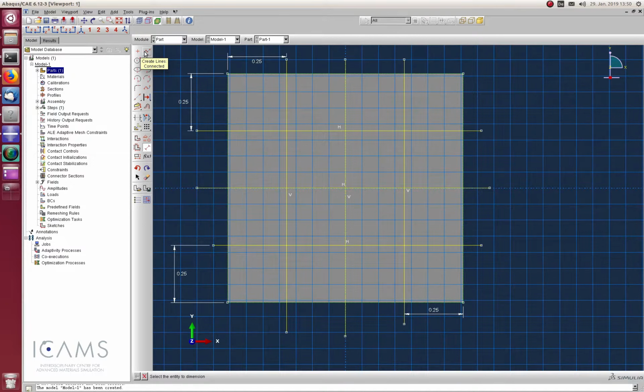And now we can find the intersection points to make the geometry as given in the task. Furthermore, now we would also need to delete some of the lines which are extra, otherwise there will be too many lines in the geometry which we do not want. The lines can be deleted by using the option of auto trim